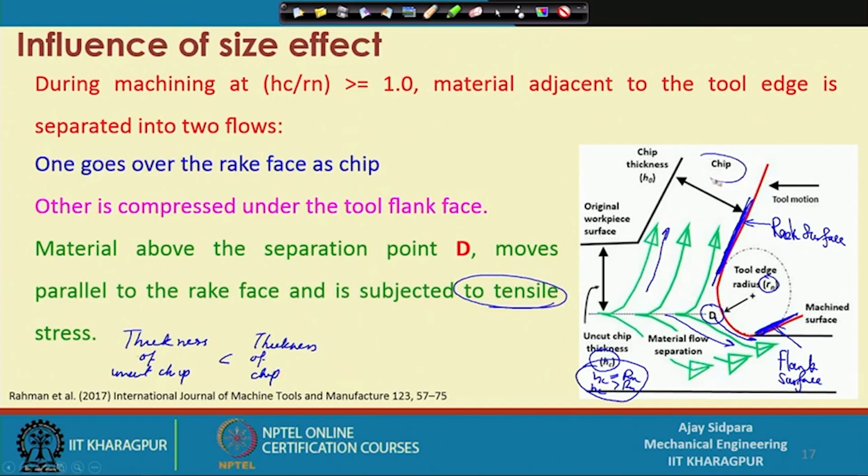So, whatever chip is coming out of there will be bigger than the uncut chip thickness, because this chip will be a little bit expanded when it is cutting out. Everything depends on the size or length of your shearing angle. So, now see the shearing angle, this particular length you consider x and this one you consider y. So, your x is larger than y. So, in this case it will be mostly in tensile stresses, and you are getting a chip out of this particular mechanism.